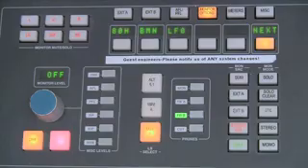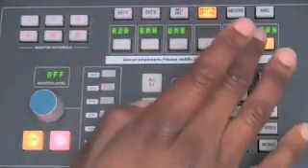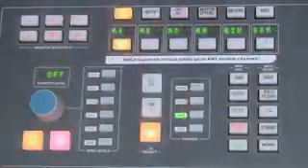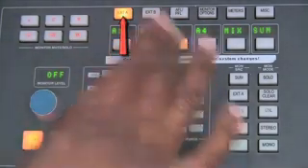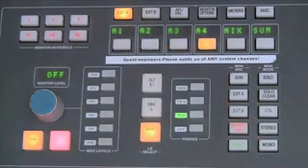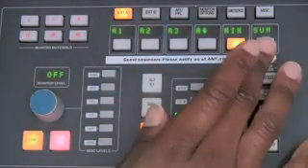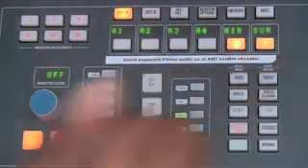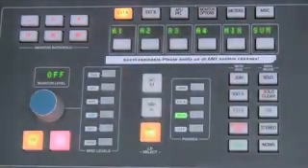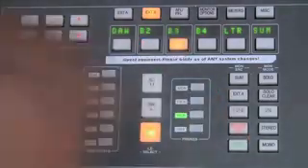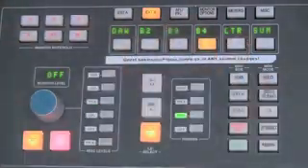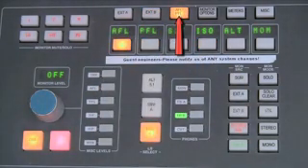You have quite a few different external input sources on this monitor section. External A and external B, each giving you 5 different sources. External A sources allow 5.1 external inputs, and external B being stereo monitor sources. So whether you have an external CD player or CD recorder, this is how you get your sources into the monitor section. The AFL and PFL allow you to select level settings for those options.